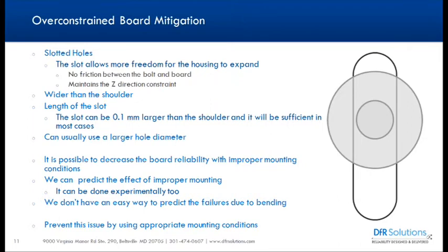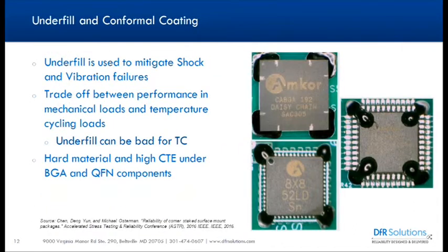Unfortunately, it's not that easy. It's not that straightforward. We have some equations that we can use. We have some strain equations. We're not 100% sure how it works when you're doing these triaxial effects on solder. Again, remember I was talking about if it's loaded in shear, it's one thing, but if you're doing tension and compression, solder behaves differently in compression than it does in tension, so it's not a fully reversed load anymore. Solder behaves the same in shear because shear goes left to right or right to left. But when you're doing tension and compression onto a solder joint, it's a little bit of a problem.